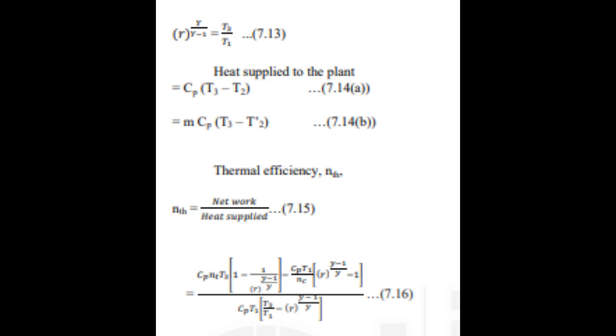7.8 Summary. In a gas turbine power plant, a turbine, which is used as a prime mover, converts the kinetic energy of the gases into mechanical energy to drive an electric generator, the load, that generates electrical power. The major components of a gas turbine power plant are the compressor, gas turbine, combustor, and generator. The function of the compressor is to supply compressed air to the combustor. The function of the combustor is to burn the fuel and thus convert its chemical energy into heat energy. The function of the gas turbine is to drive the electric generator which generates electricity.